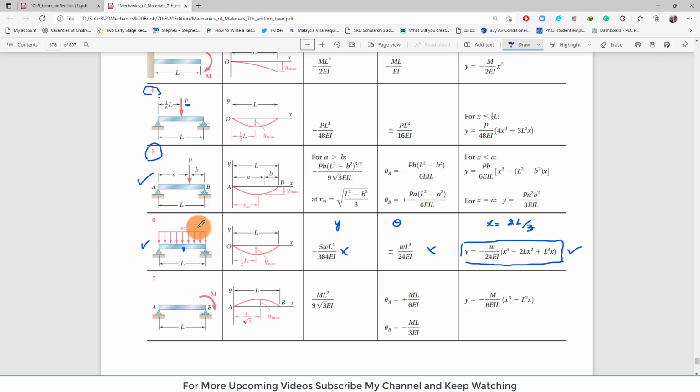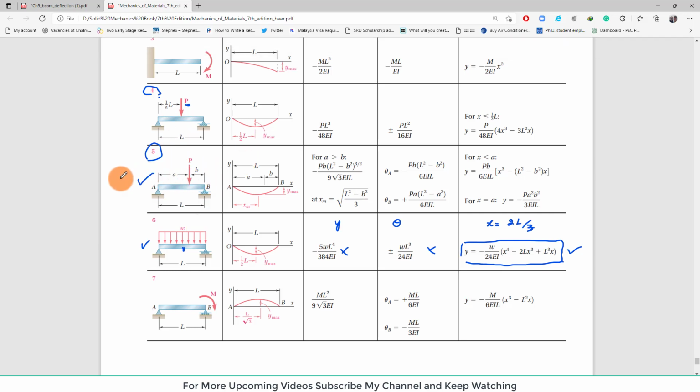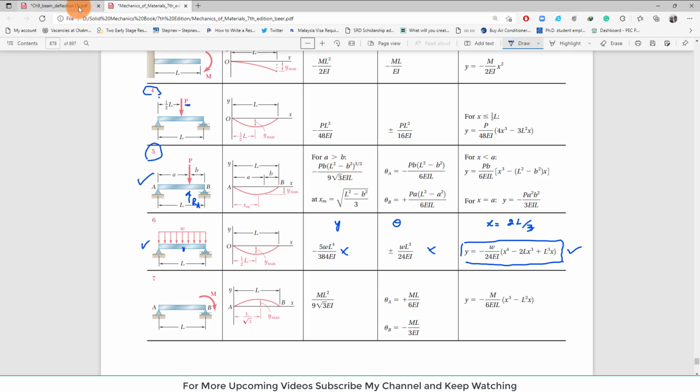So our case is similar to case number 5, but here the loading is downward, and in our case our loading is upward, RA is upward. So it's okay, we will use the negative sign as positive, because here for the downward force all the values are negative. Clear? So we will use the sign convention in order to get our desired result.